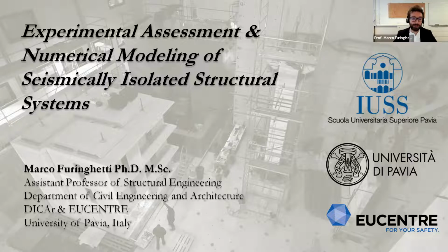Let's say generally seismic isolation, because maybe we are considering a structure which is already very flexible. As the flexibility increases or the stiffness decreases, we know that automatically we have a sort of period elongation, but just due to the flexural behavior of the building itself. And so maybe we don't need any isolation system, but this can be checked, obviously.